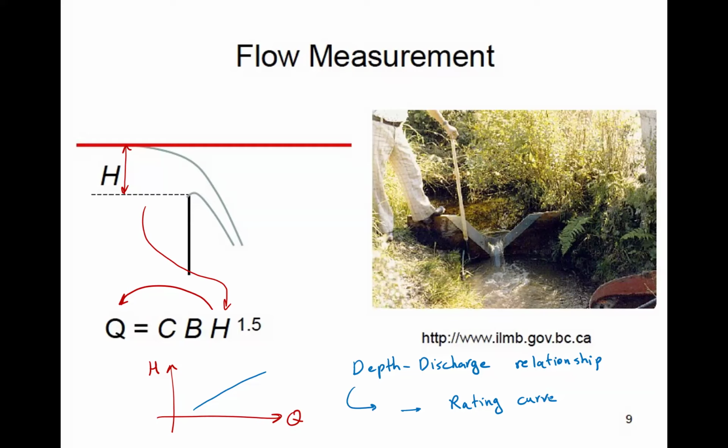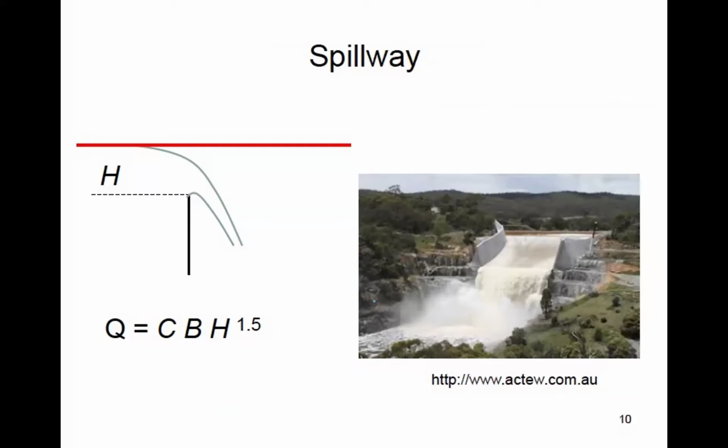As we said, another very common situation where we have weirs is in spillways. You typically don't use spillways for measuring flow unless it's a really, really small flow and channel. They're typically used for controlling water level and discharging floods in a managed and controlled way, and storing water if it's a big reservoir for hydropower, or providing head to a powerhouse or things like that. So the application is slightly different, but the same equation, nothing really different. And the same weir equations. C might be different again based on geometry and so on, but everything else is really the same.